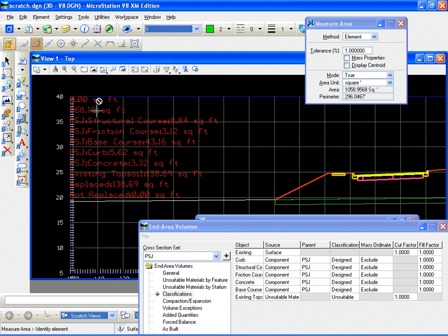And the reason for that is the amount of fill required to fill my unsuitable has automatically been included in this calculation. So if I measure this, I get 277.3. Divided by 2 is 138.65. Notice how the 138.65 matches the existing topsoil removal. If I add the 138.69 to the 529.48 determined earlier, we get 668.17. That matches the total amount of fill required for this section.